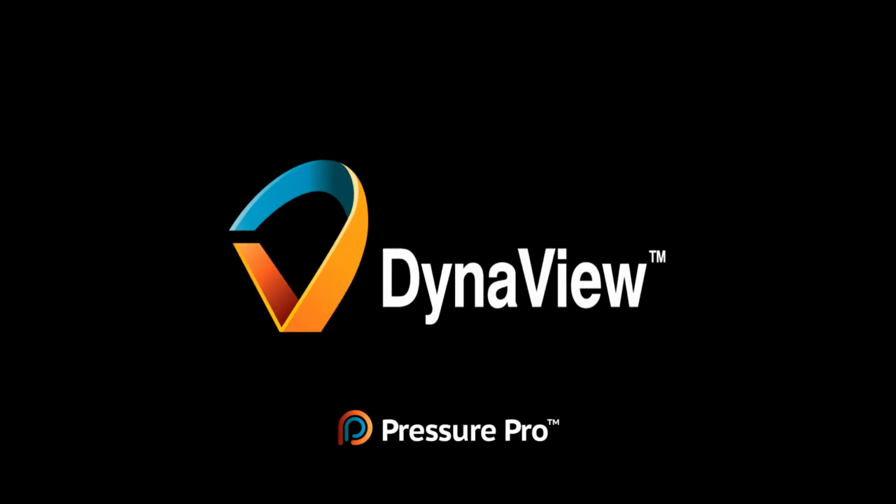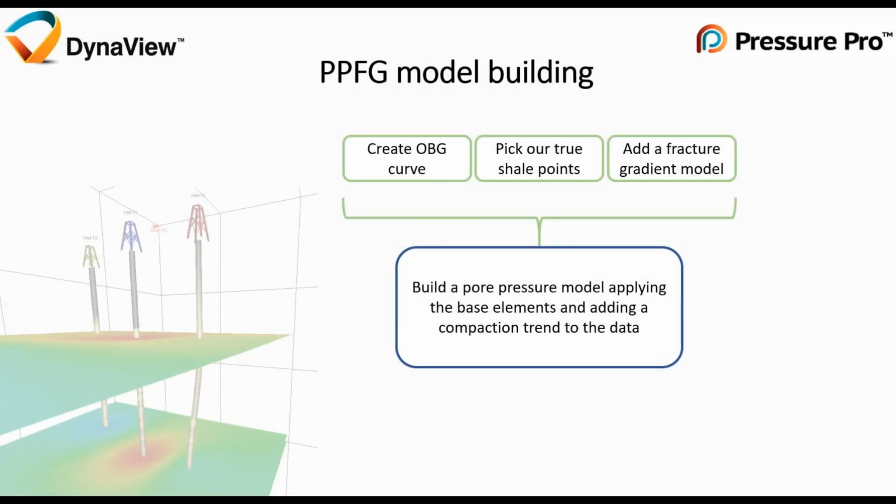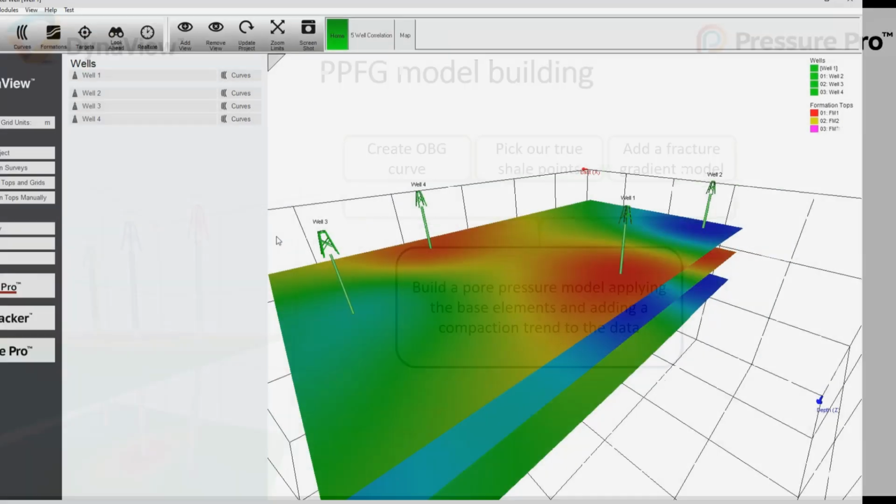In the first movie we covered data import and model building. We will now dive straight into the pore pressure model building. The model building process works according to the workflow shown here. First we build an overburden model, pick our true shale points, define a fracture gradient model, and then we'll pull these various elements together into the pore pressure model.